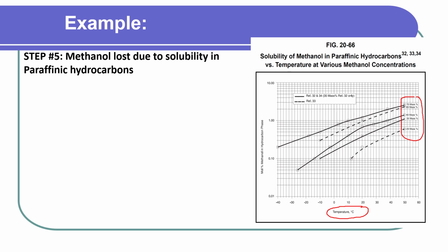So the first step will be that we're going to use this chart. How are we going to use this chart? First thing, we need to estimate methanol loss due to hydrocarbons, solubility in hydrocarbons or liquid hydrocarbons.